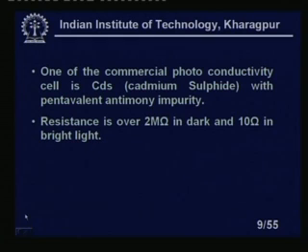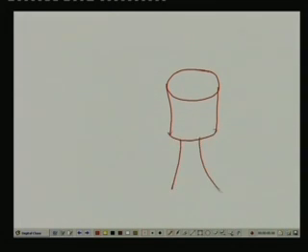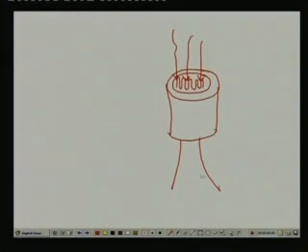It looks like this, if I take it. So, it looks like this. I mean, if you look at the encapsulation, I have drawn a little bigger. 2 leads are coming up, and they have a transparent plastic cover on the top, unlike the other semiconductor devices, and you can see these photoresistors inside, right. So, light should fall on this one. If you bring it to the sunlight, you will find immediately the resistance, if you measure the resistance across these two, immediately it will reduce, right.